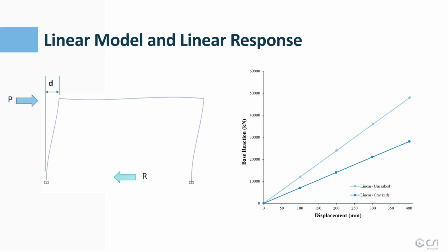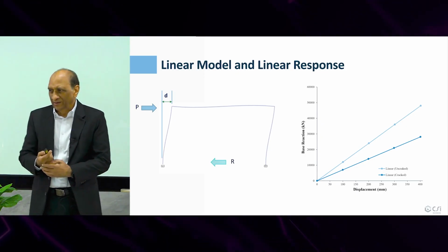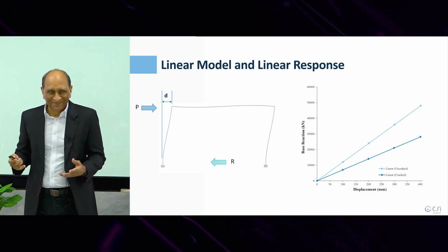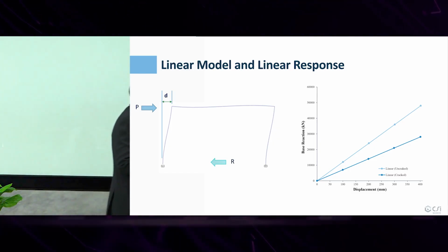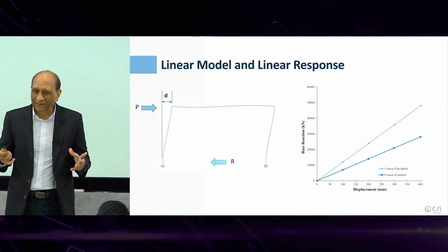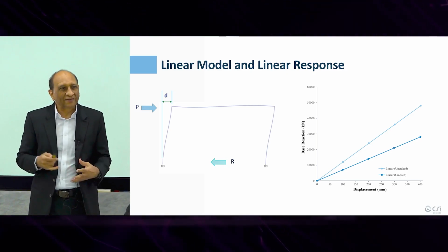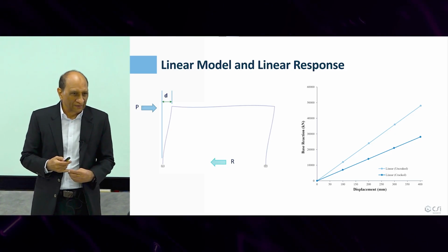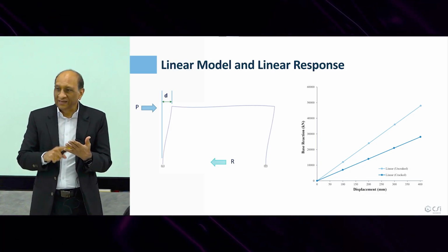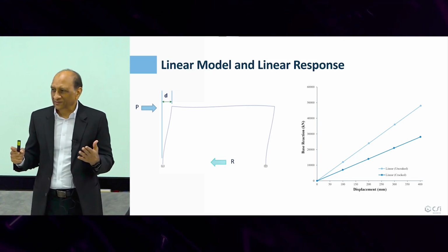And this is, to me, one of the biggest challenges or problems in design codes, the cracking factor. I am deadly against it, but nobody listens to us. The problem is that these cracking factors are highly arbitrary, but we have no way to get out of them. In nonlinear analysis, we get away from them, but in linear analysis, we use cracking factors. The problem with that, number one, is that they are arbitrary. And they differ in all the codes. If you look at the table that we have, oh my God, so much variation.